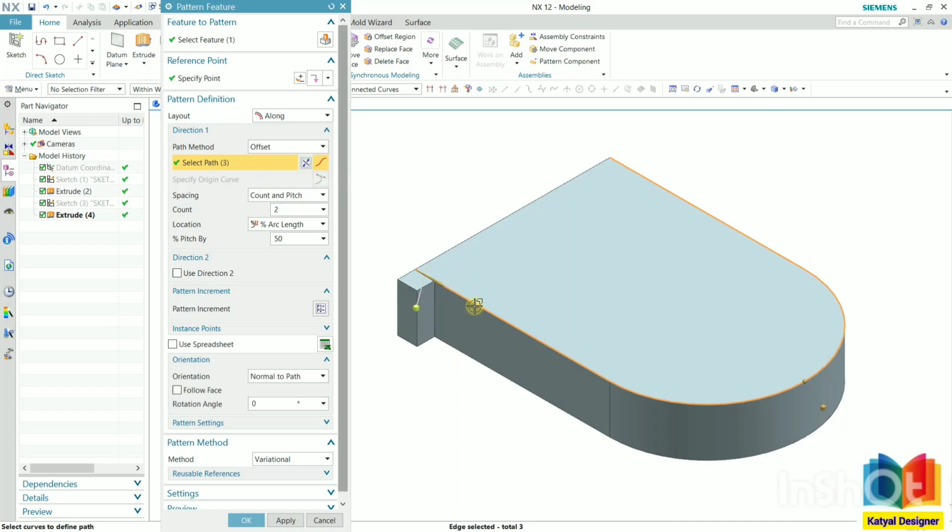Okay, after that we have option like rigid, offset and translate. So I can select offset. Offset means it is going to create pattern at some distance. So number of counts, let's say I want 15 and the location, it is showing the error because we need to specify this proper value. So let's say this value is 7. Now we have proper pattern.